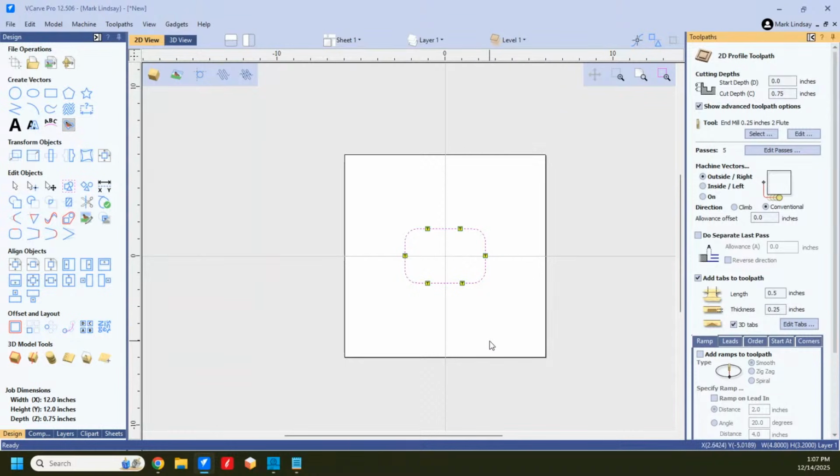So you gain a little bit of speed when you're doing 3D tabs in that the X and Y never stop moving. But what you've just done is, and I wish I could blow this up a little bit, you've taken the whole combined thickness of 1/4 inch, and the only thickness of that tab that is 1/4 inch is right in the center.